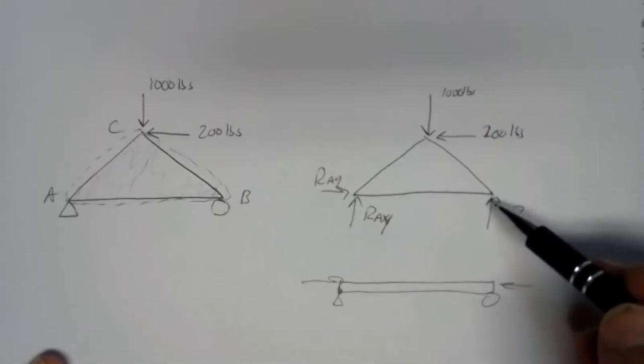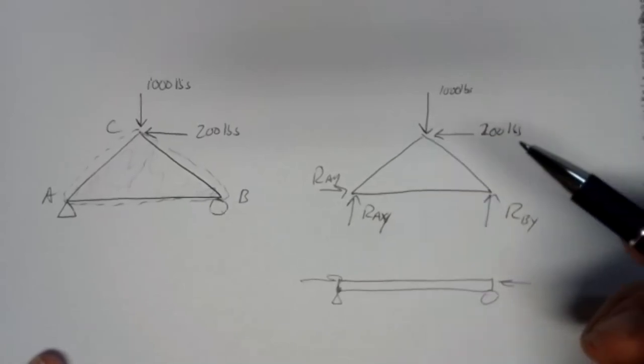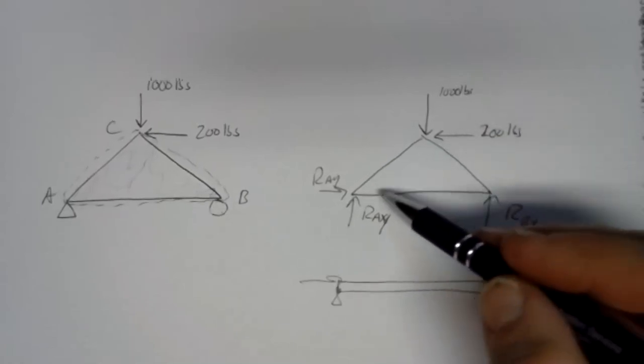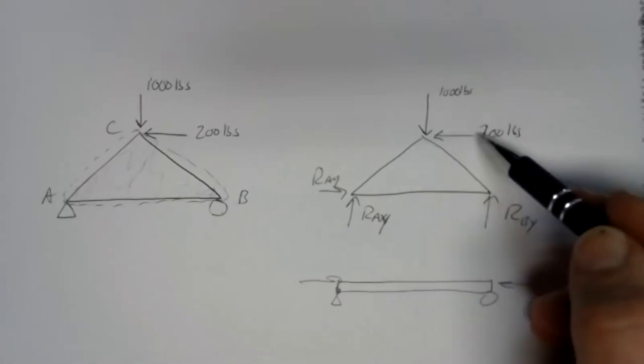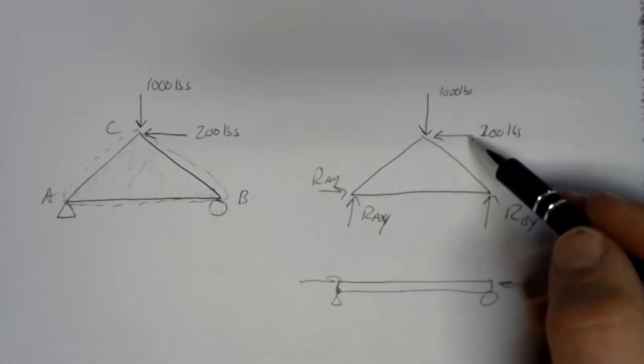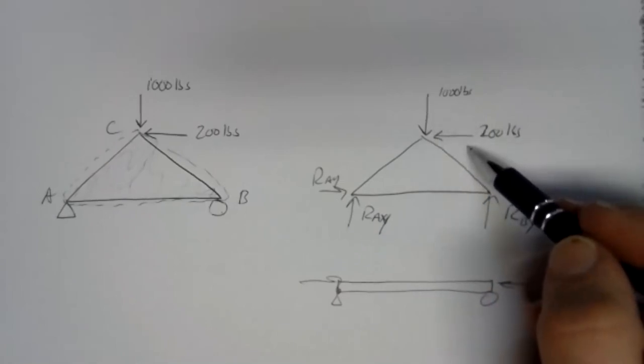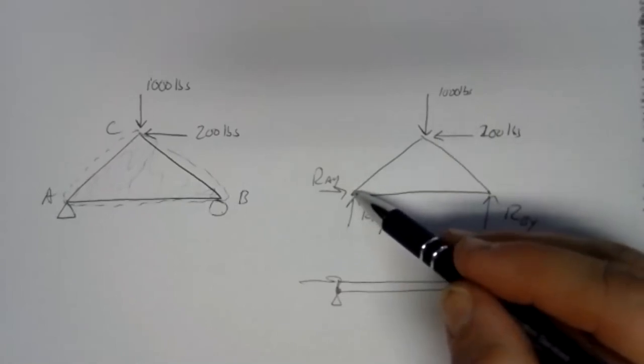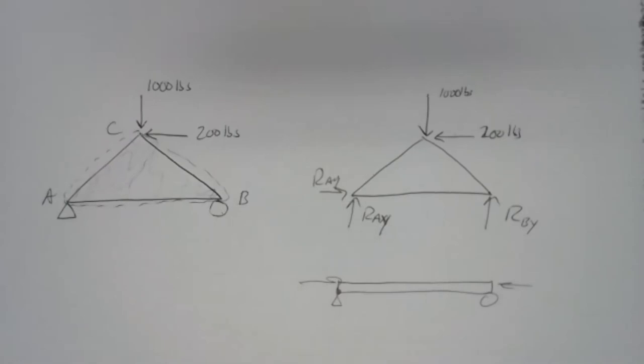Or 24 feet across and 6 feet up. That'd be another common pitch to a roof. So the 6 feet is a pretty good arm. Both of these forces up here have a moment about our pivot point A. And so moments we have to be a little more careful about. It's not going to be just the vertical forces that cause moments.